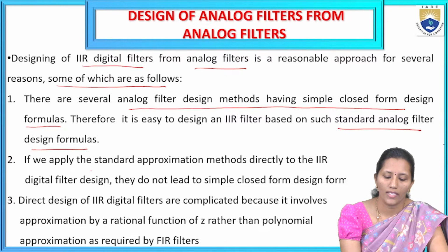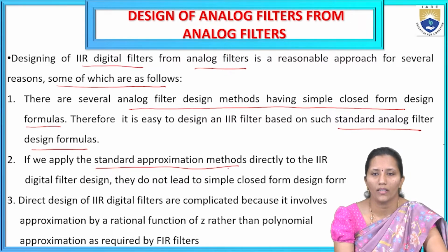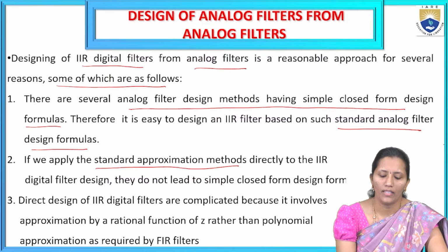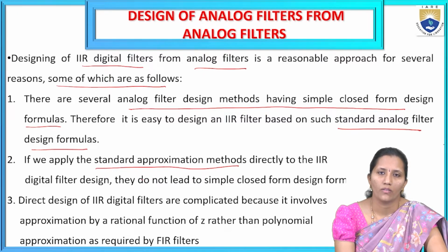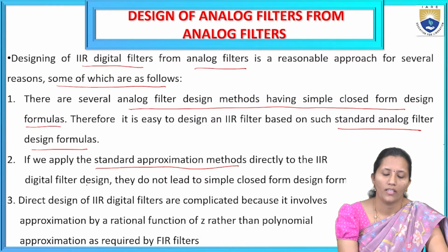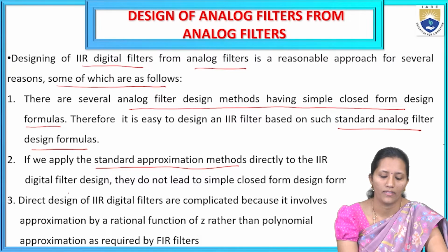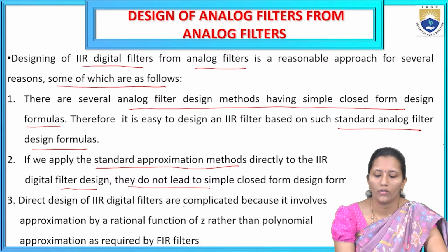If we apply the standard approximation methods directly to the IIR digital filter design, they do not lead to simple closed form design formulas, because the output depends on the previous output values. The IIR filter is numerically not stable. So that's why, if you apply the standard approximation methods directly to IIR digital filter designing, they do not lead to simple closed form design formulas.